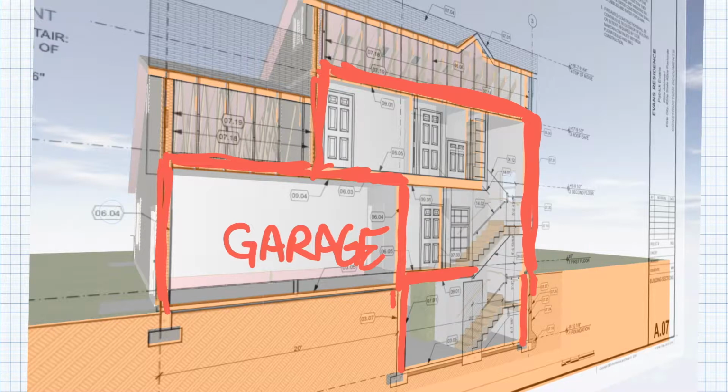Now, here's another factor to consider, is we have earth in this area. So this earth here is actually creating some insulation for the basement area, but it's only effective once it's 3 feet deep. So that's why we would add a little bit of insulation for the first couple feet of the exterior.